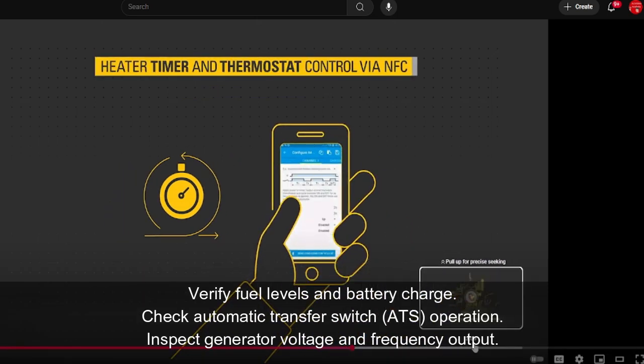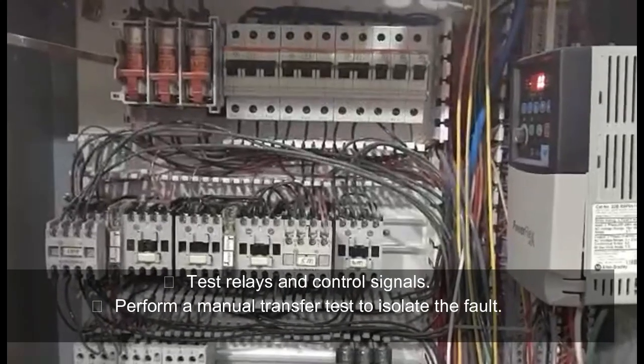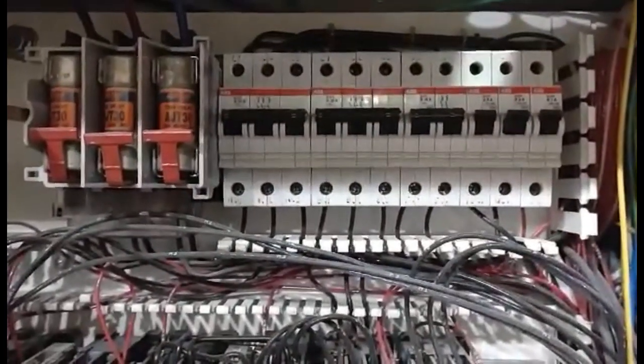Number 3, inspect generator voltage and frequency output. Number 4, test relays and control signals. Number 5, perform a manual transfer test to isolate the fault.